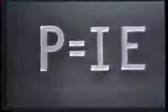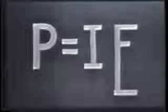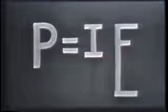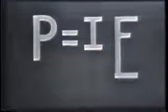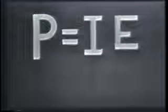Power would be transferred from one voltage current level to another. Since power is the product of current times voltage, an increase in voltage by means of the transformer must result in a decrease in current. And likewise, a decrease in voltage by the transformer must result in an increase in current.